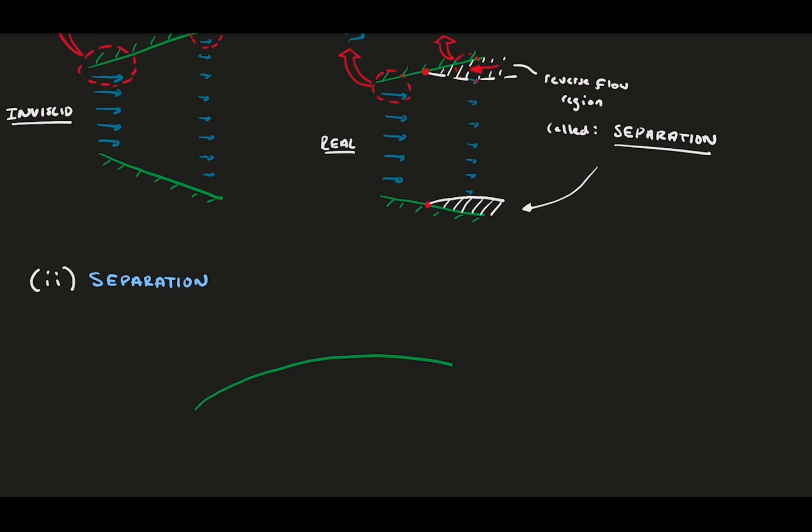Consider flow over a cylinder or sphere. Generally, when the flow hits the front of the cylinder or sphere, it accelerates as it is forced to the top of the curve, or I like to think of it as going up the hill. Then, when it goes back down the hill, it slows down. This is because locally, in the front of the cylinder the flow is converging, and in the back it is expanding again. Zooming in, we see this.